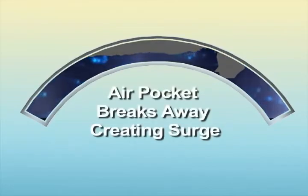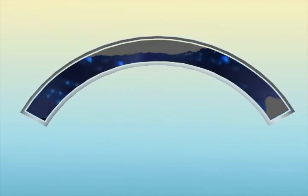The second and more likely occurrence is that the increased velocity will cause all or part of the air pocket to suddenly dislodge and be pushed downstream, leading to a high-pressure surge or water hammer. Serious damage to valves, fittings, gaskets, or even line breakage can occur. This is the most serious of the possible consequences of air being allowed to accumulate in system high points.